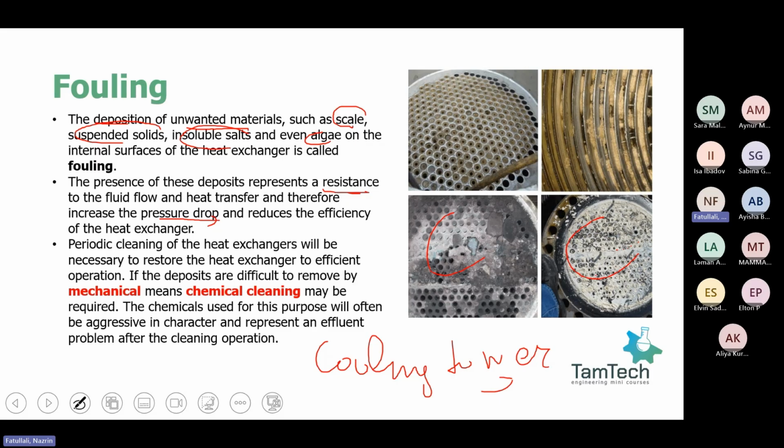Firstly, prevention always works out cheaper than mitigation. That's why we use chemical injection beforehand. For example, if you assume that you could have some carbonate scale, you could inject some chemical based on its dose in order to prevent it. But if prevention is not achievable, then we have to suggest mitigative actions.